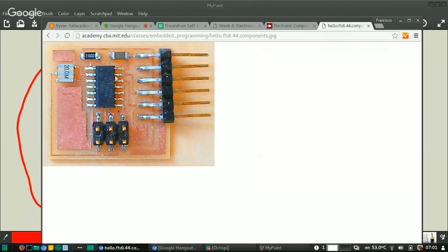For example, in the library file, I selected the ATtiny44 SSU, because it's obvious we need a chip. Then in the diagram it's also listed FTDI header and ISP header, so I selected those as well from the library.